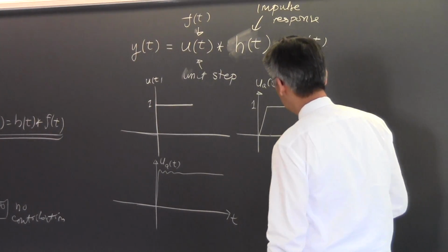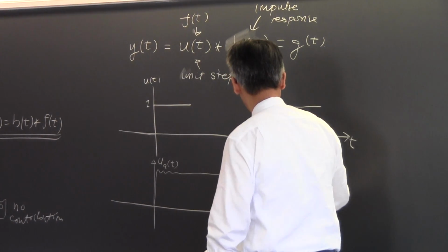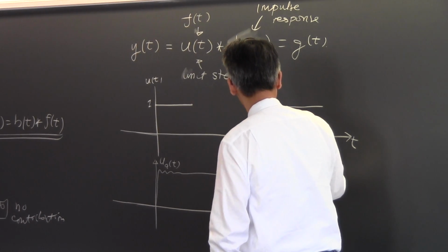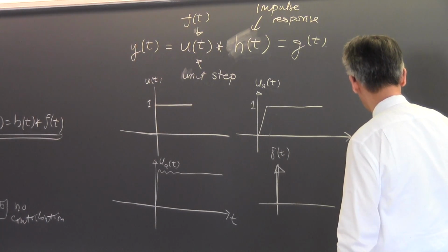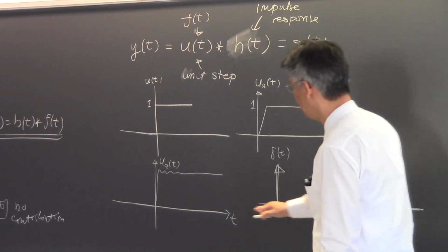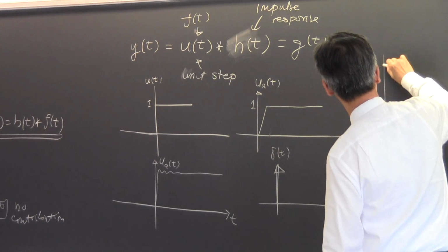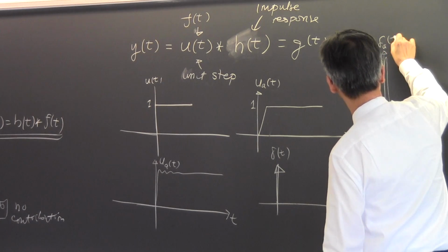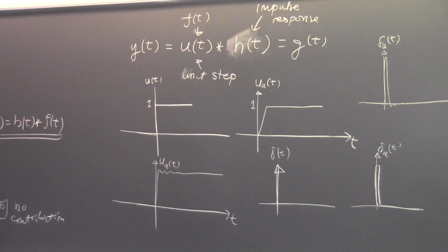So even for an impulse function, if you differentiate this first function, it's supposed to get an impulse that looks something like that. But if you differentiate this one, you're going to get an impulse that looks something like this. This is an approximation. If we differentiate something like this, it more or less looks like something that goes to a very large value and maybe rings a little bit. So this is an approximation to the other function. In the lab, you usually get something like this, and not quite close to the impulse.